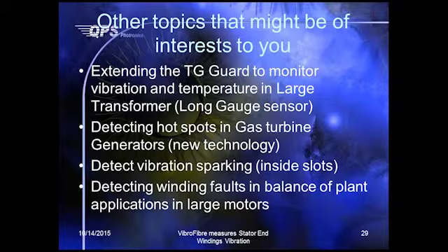So you have the option of placing this long gauge sensor in the very narrow gap inside the slot, and you can now measure in-slot vibration. And that has been most difficult to do because nobody makes a sensor that thin that can fit.